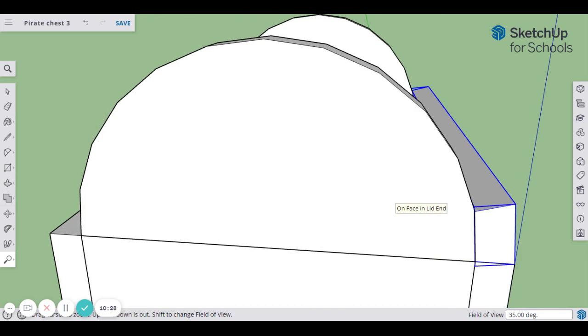I'm going to get my rotate tool again, so Q. And this is kind of neat. We're going to do an array around a circle, and it's something I haven't done a lot of, so bear with me if I make a mistake. But hit that left arrow again to constrain it. So we have a rotate tool, but we're going to hit control, similar to what we did for copying. So we're going to copy this slat around to the other side.